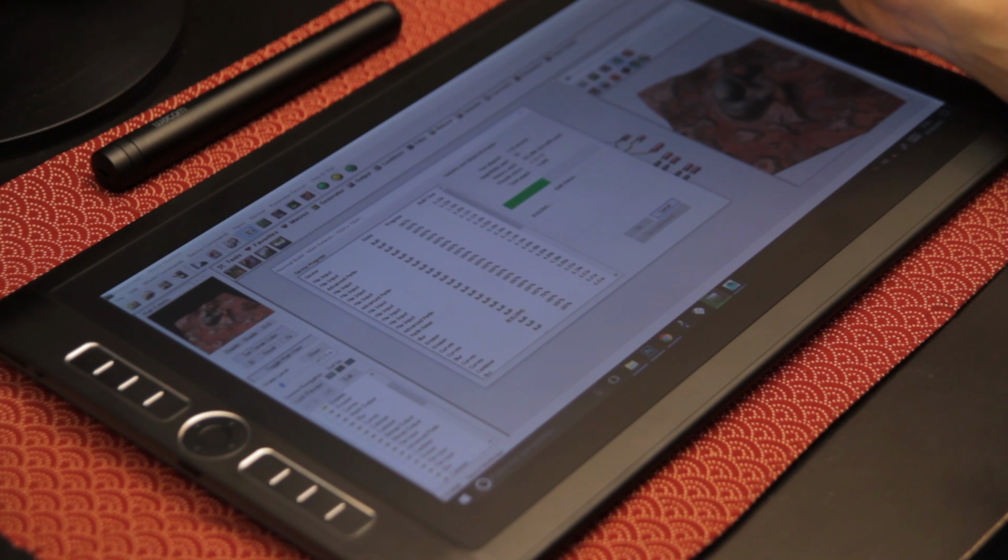The nice thing with World Machine is that when you compute all the nodes, it stores the result in high resolution for each operator, so you can just visualize the effects of each of them separately. So here it's computing pretty fast. It's not as fast as on my workstation, but still pretty decent. Here I'm computing just at 1K resolution for the preview, which is pretty fine for a preview already, but we will end up using 2K or 4K resolutions for the final output, and it's gonna take much longer, of course.